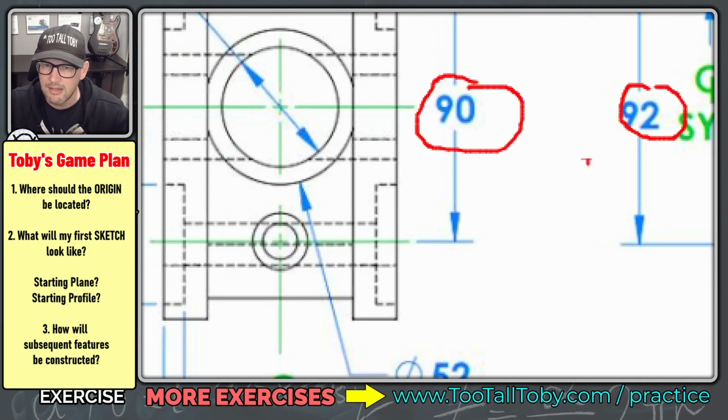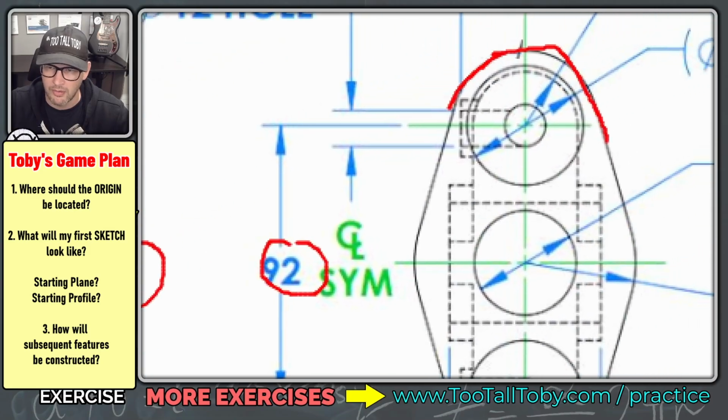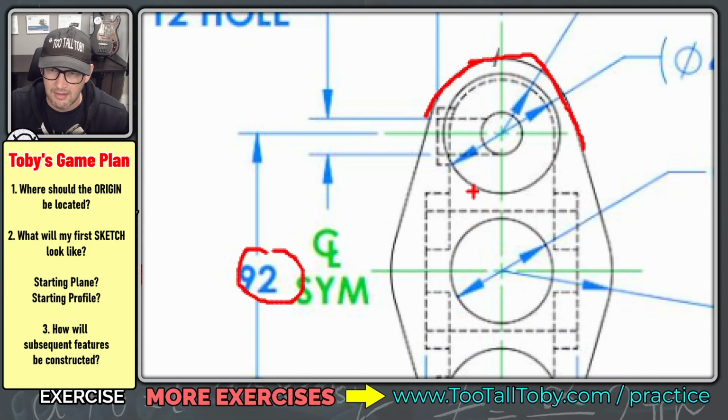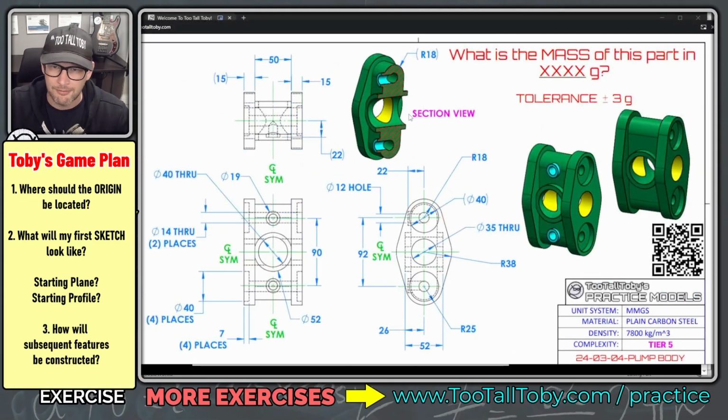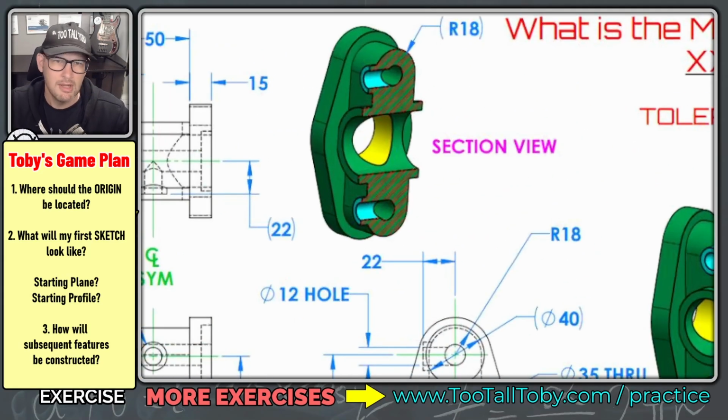Now, you can interpret that when you look at the drawing here, and you notice that the dashed line is almost coming to the point of tangency, where the dashed line is intersecting that circle a little bit lower than the point of tangency up top. You can also decipher it from the section view using the same observation, this tangency point down here compared to running into the circle up top. But it's definitely a little tricky and something that you want to be on the lookout for.